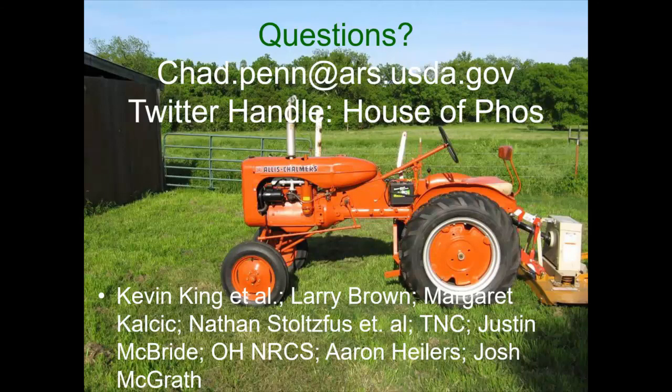And if it goes anaerobic, it's iron oxide-rich media, it'll start to dissolve a little bit and could release some of that phosphorus with it. So we're doing research on that right now. But that's exactly why I've not built an iron oxide structure from the bottom up. So far, I'm keeping those top down. I'm hoping to be able to do it from the bottom up.